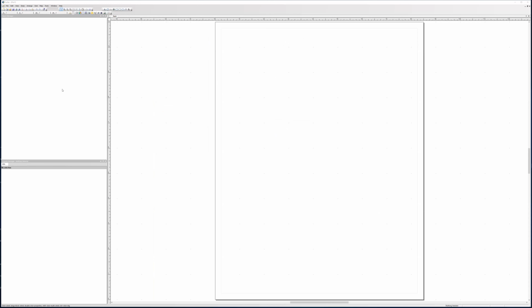It's a usual kind of Windows type of software. On the top, you can see the toolbars, right? On the upper left, you can see a window where SURFER will show you what kind of objects it's working with. And the window below is the property window. Whenever you select an object, let's say an axis or a surface or whatever, here you can adjust its properties, okay?